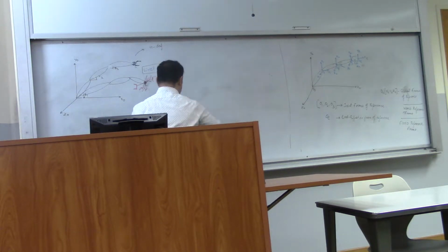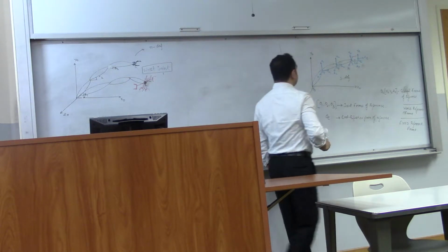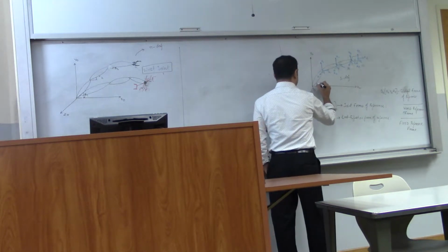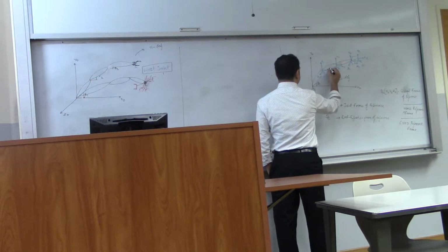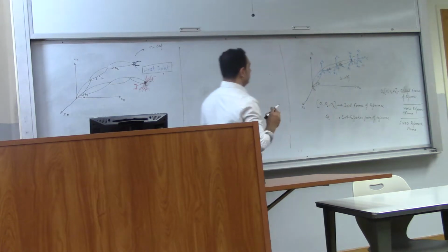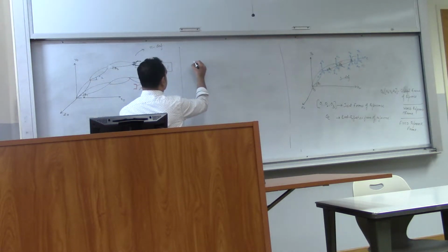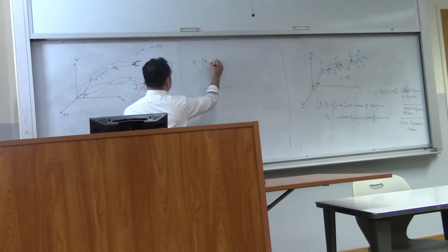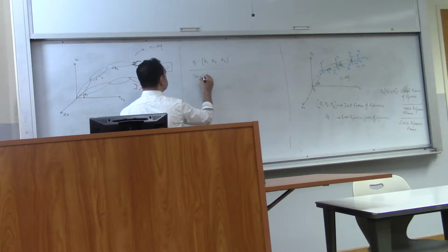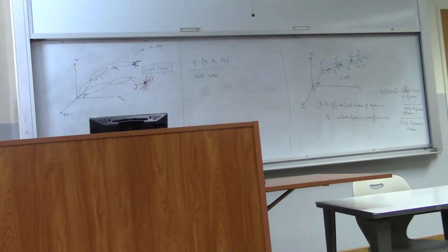So these joint displacements, let's say we have a 3 degree of freedom manipulator, 3 DOF. The instantaneous position of the manipulator is defined by the angles here. This is theta 1, this here is theta 2, let's say this is theta 3, okay, and this is theta 4, but let's ignore the wrist for a second. Let's only focus on the links. We'll talk about the wrist later. So Q, made of theta 1, theta 2, theta 3, is known as the joint vector. Okay, it will define in what position the manipulator is currently in.